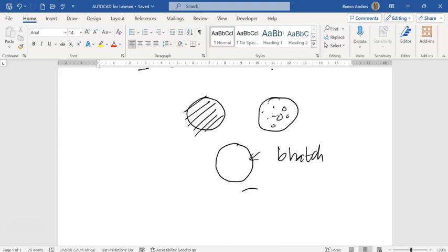Right. Now, if your boundary looks like this here, with a little opening there that you can't see, it'll hatch right through there until it finds another boundary, and you go, oops, that's called bleeding, okay? So you must give it a completely enclosed boundary to hatch successfully. So AutoCAD looks for that, okay?